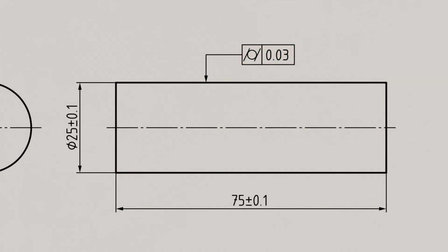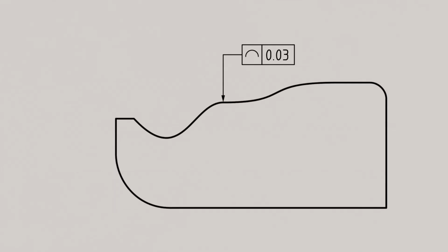So far, the consideration of geometric elements has essentially been limited to two basic geometric shapes, the straight line and the circle. However, components can also have more complex geometries that can no longer be described by these simple basic shapes. The illustrated example shows a thin sheet metal part whose upper edge cannot be described by either circular or straight segments. Even such complex line profiles must be toleranced in form to ensure that they do not deviate too much from the ideal shape of the CAD model during manufacturing.